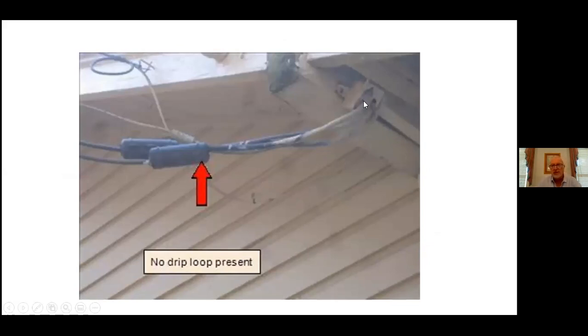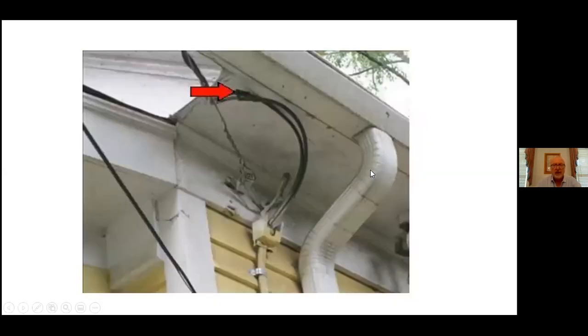So we'd make sure that this was properly secured to the side of the house. Here's another one where you can see it's actually the complete reverse of a U. Now we're going over the top, and we really need that to be brought down lower right here. Again, here the mast is attached to the side of the home, and the wire goes in through this hole right here into the attic space, and then over to where the electrical panel would be.